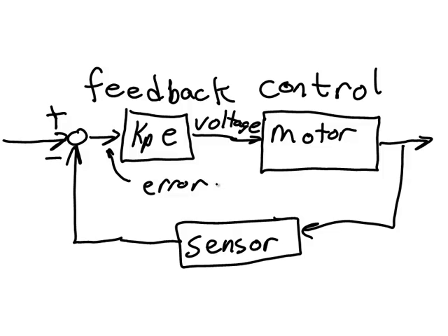So the units on this error will be position units, something like millimeters. Because the input to the controller is in units of millimeters and the output of the controller is in units of voltage, the value Kp is a kind of unit conversion that converts millimeters into voltage.